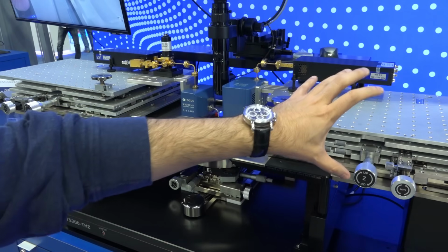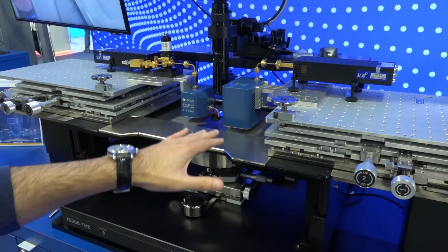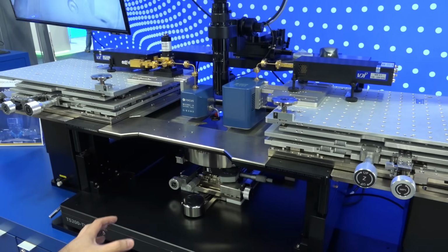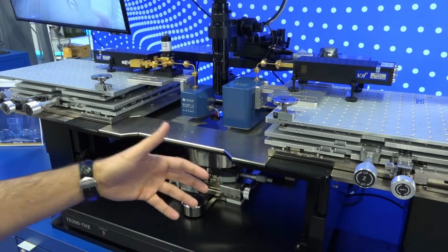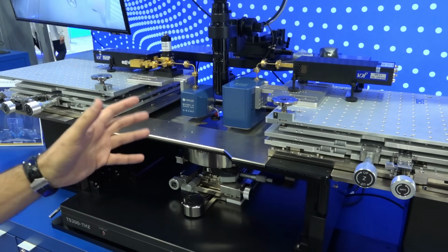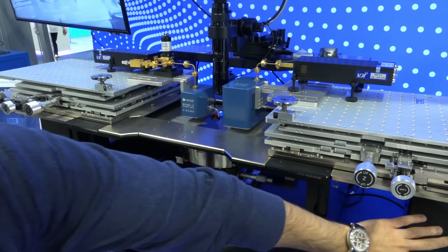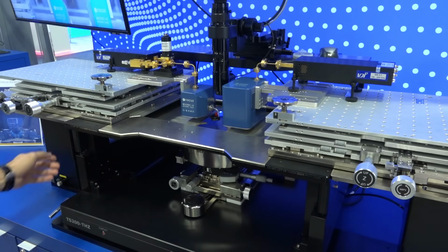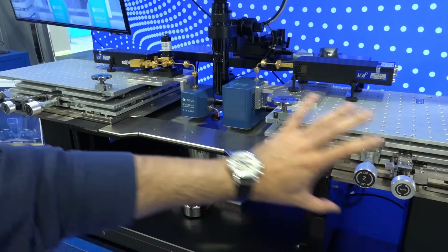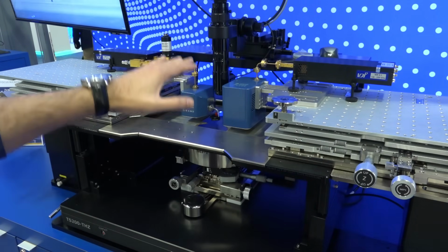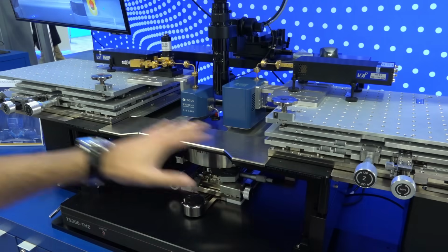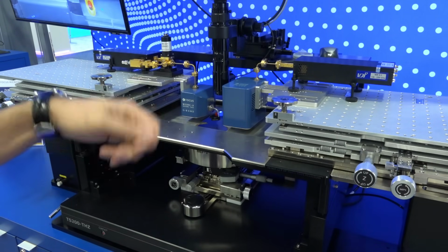But this has a lot of mass, and now you need planarization between your probe and the entire probe station. That's a big challenge. Now, MPI has a huge range of probe stations, and in this particular one, they have these dampeners sitting on the left and right side of the probe, bearing the weight of these large manipulators. So as you lower and raise the probe, these all move together, maintaining that really good repeatable contact.